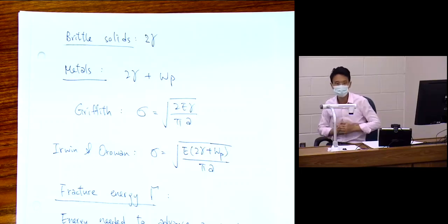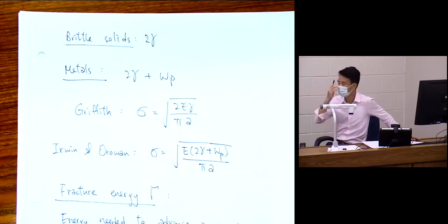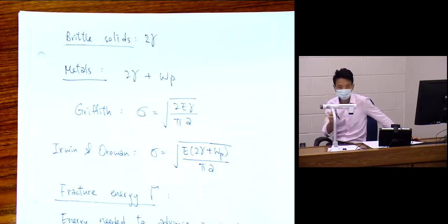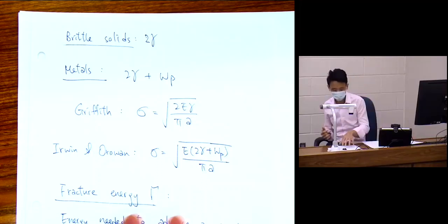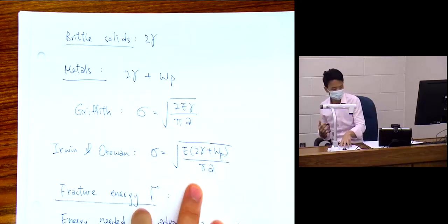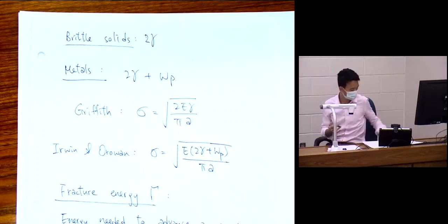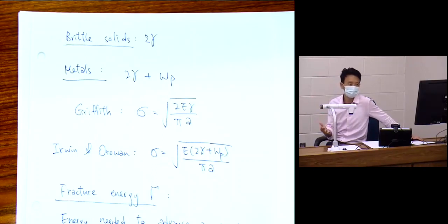In addition to surface energy, there's also a large amount of plastic deformation at the crack tip, and there's some energy dissipated because of that plastic deformation process. Okay, so that's the first difficulty, so to speak, in applying it to other materials, and indeed we talked about that also, very quickly. It was solved or circumvented by Irwin and Orowan. Well, because we know this is plastic deformation.